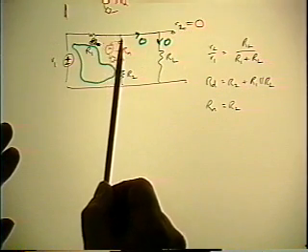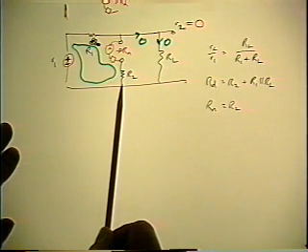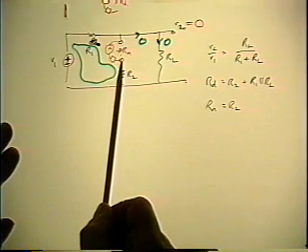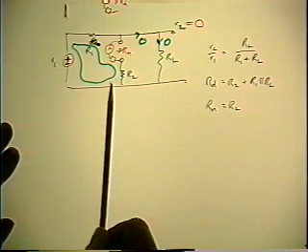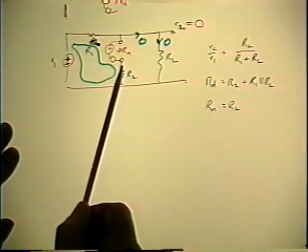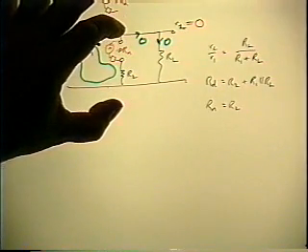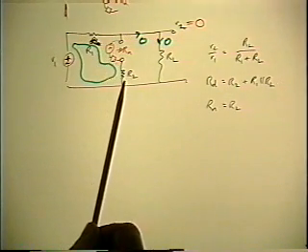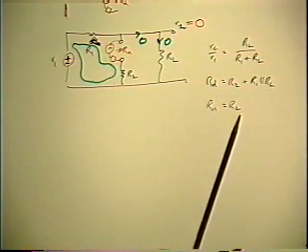And that same current has to flow through the second source and is going to cause a voltage drop across R2. But in order to get the null, the voltage that you've stepped down through the second source has to be the same as the voltage you step up across R2. So there's a non-zero current around that loop. That's why the impedance seen by the second source is R2, because you got zero voltage across that series combination. The current through R2 is the current through the second source, and they have equal and opposite voltages across them. That's why the impedance seen is R2.